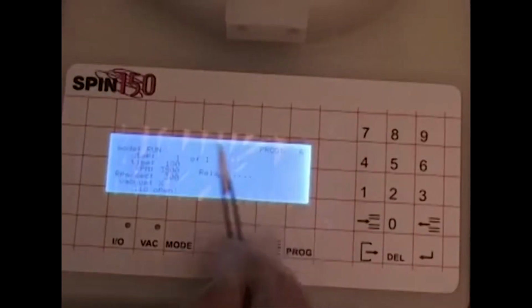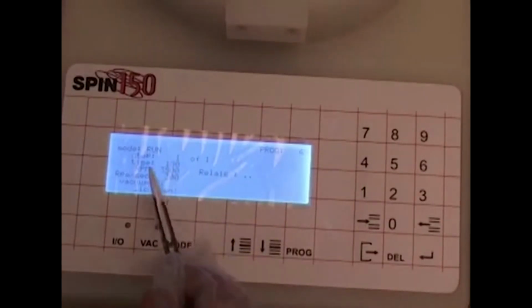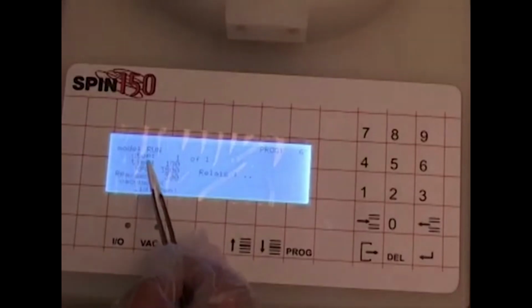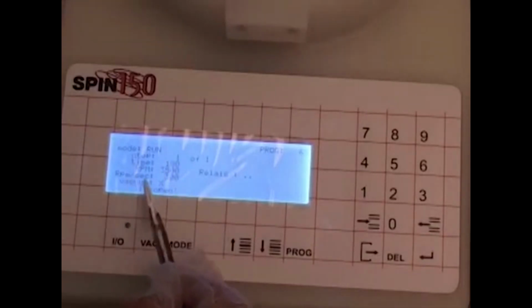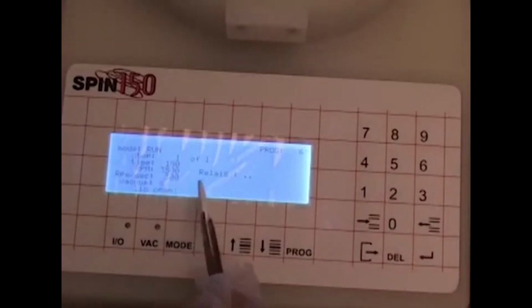Corresponding to this program number, the steps in the program are illustrated in this particular region. As you are seeing here in the run mode, step 1 of the program illustrates an RPM of 3500, attained at an acceleration of 300 RPM per second, and the hold time is about 180 seconds, with the vacuum option on so that the wafer is pulled down while the spinning happens. Then finally you have to change this program to suit your requirements.